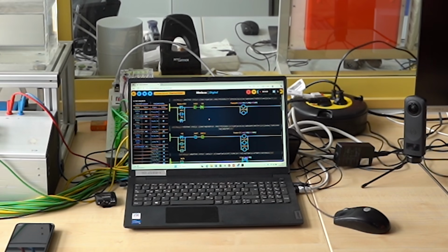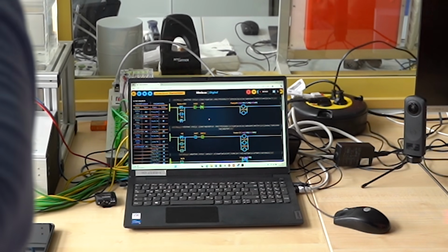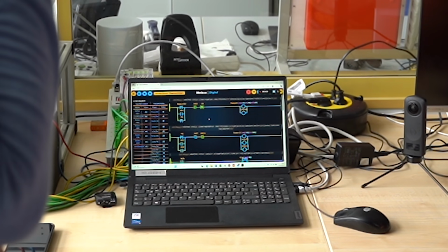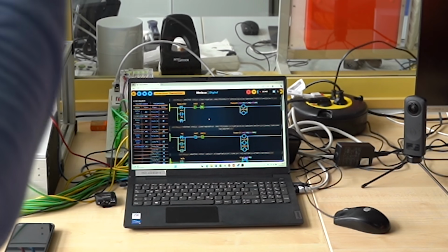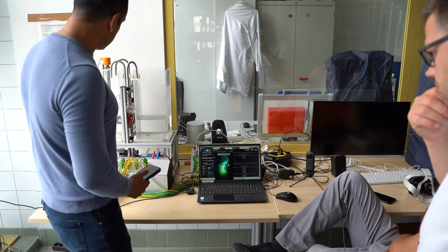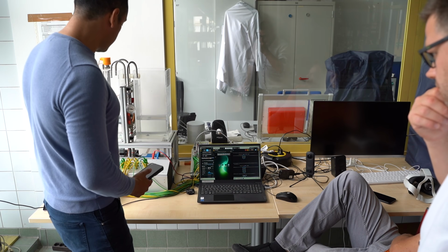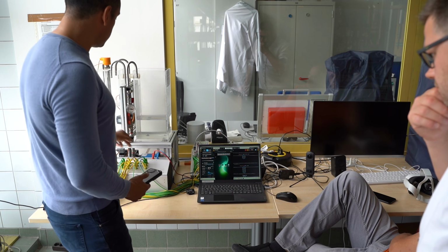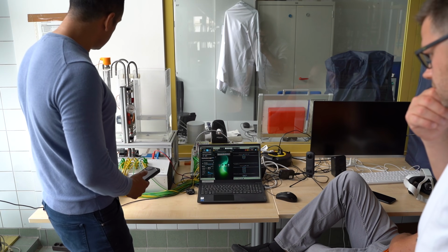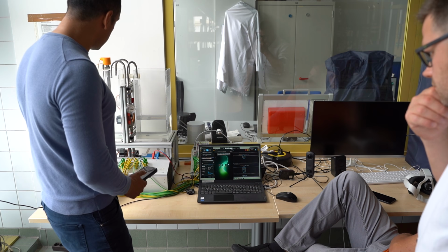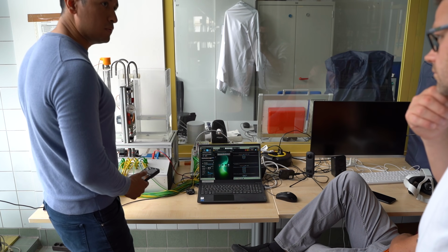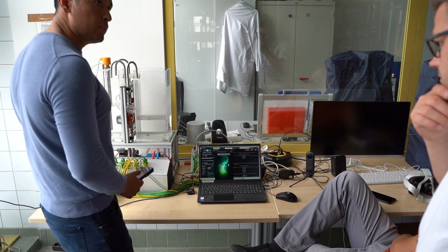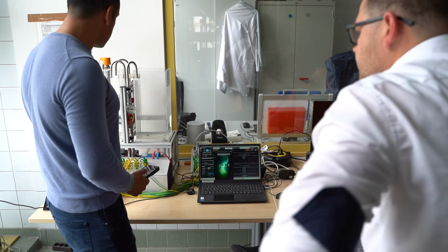So what I was thinking, now that you mentioned it, yes, it is possible that everyone sees the feedback on the system. Right now, I never had the idea that it could be needed, but you're right, it makes sense. Like if we have a group of 10 people, if the water level is up to this level, then you can send water with the 2 pumps. But once you reach this one, you shut down one of the pumps, so it's easier to control the last field. And once it reaches here, the system stops automatically. So that's how the logic was done.